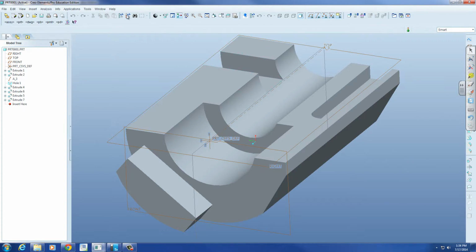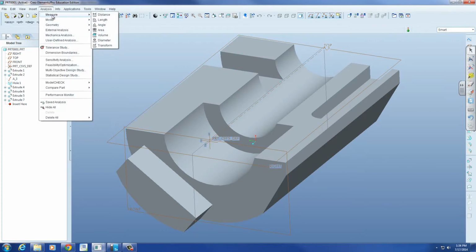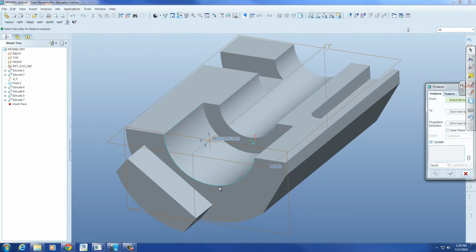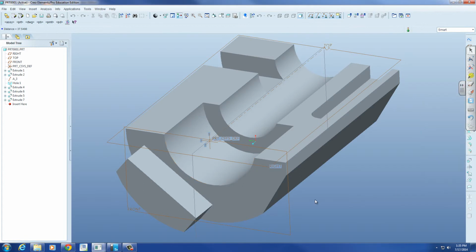So the question was, is this going to need to be hollow? If I measure the distance from here to here, that's over an inch thick. It can't be solid in a PC-ABS blend. Now, if you're going to go with something with thicker walls, you may have to add glass fill or mineral so that you can have those thicker walls. It actually gives it more structure so that it doesn't sink. We're going to talk about that later in the books. So I think we have to core it.